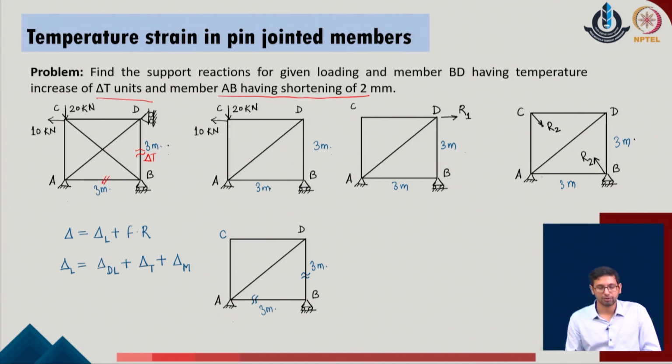As a first part of the given system, we consider that the external system is converted into a statically determinate system subjected to the external loads. At the same time, we have a redundant system 1 which is subjected to the redundant value of 1 unit. We have a redundant system 2 which is also subjected to 1 unit of the load.